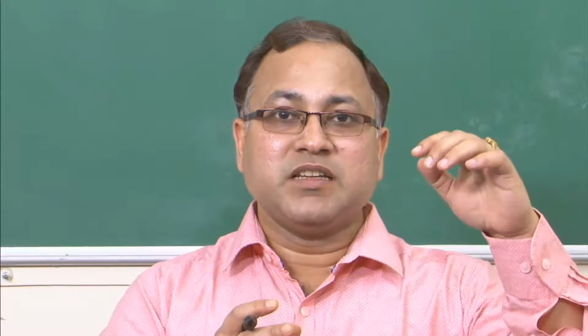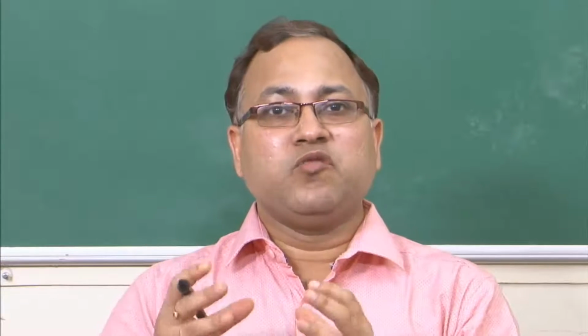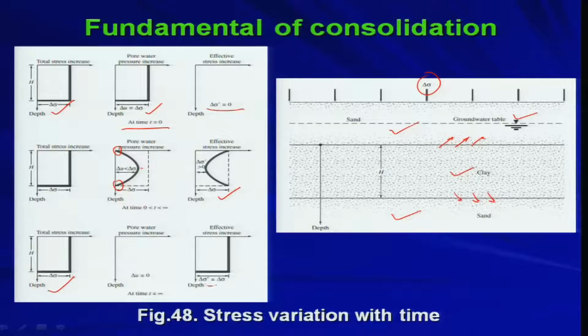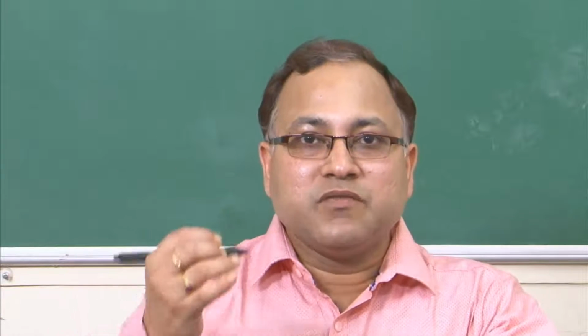Now what will be taking the total stress then? Whatever stress increment you have given, the whole stress will be taken care of by the soil solid. That means effective stress will be increased by the same amount. So, your effective stress delta sigma prime is equal to delta sigma. So, this is happening with respect to time.